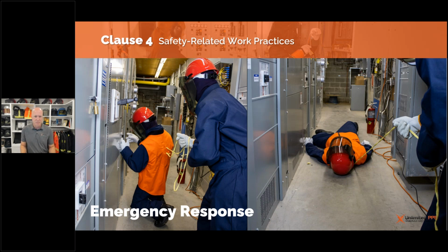This example here is a small electrical room. This worker that's in the forefront working on the equipment, we're mocking a work task here. They're wearing a vest because their PPE was purchased previous to having the escape strap option. So they're wearing a vest over top that's made of arc-rated fabric, and the escape strap is built into that vest. So if they need to be rescued, the secondary person can do so.